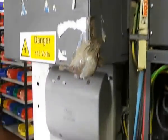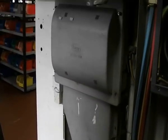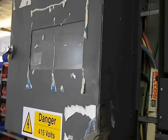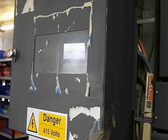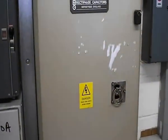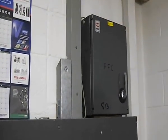The power to the factory is derived from this 300 amp TNCS service, and the cables then pass through a CT chamber, and the CTs supply a digital energy meter, which indicates that the power factor at the moment is 0.9 or thereabouts, and here is the power factor correction of unknown capacity. There's a broken switch on the front, and it's controlled by this switch fuse over here.